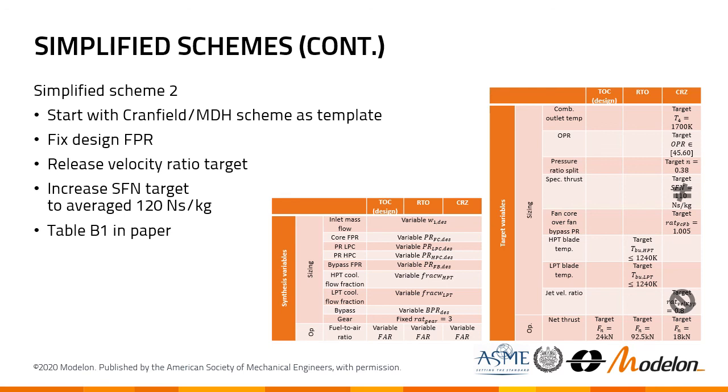You can again deduce that this scheme is probably too simplistic. Achieving the specific thrust target only through variation of bypass ratio can only work by increasing or reducing the relative influence of the core jet velocity, and as the jet velocities only vary mildly between the hot and the cold stream, say maybe 20%, the strategy is likely poor and also somewhat fragile. Additionally, varying the bypass ratio to achieve the specific thrust target influences the jet velocity ratio and probably moves it away from its optimal value.